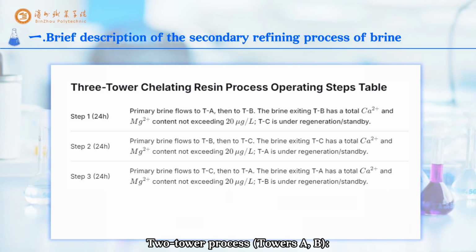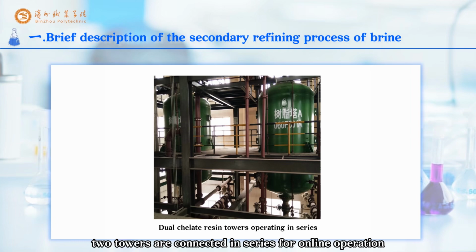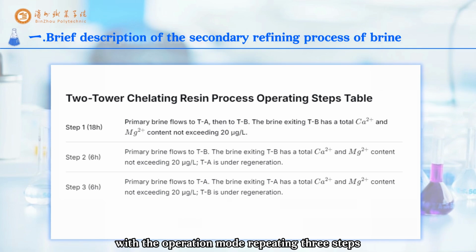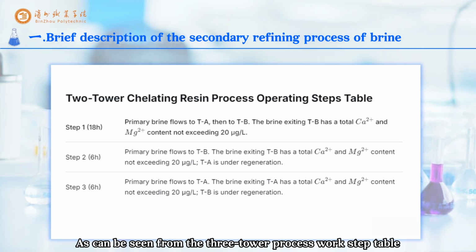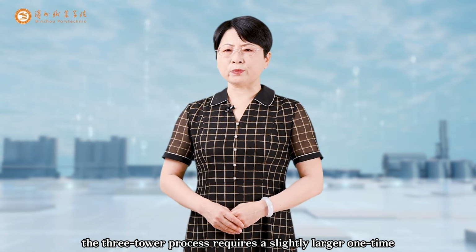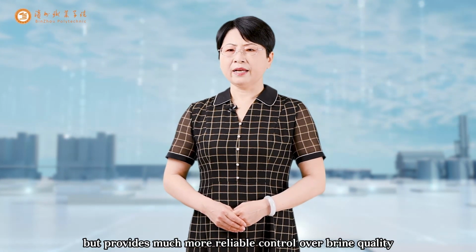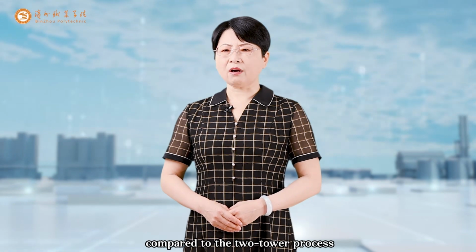In the 2-tower process, towers A, B under normal circumstances, 2 towers are connected in series for online operation. Then, 1 tower runs online and the other is offline for regeneration, with the operation mode repeating 3 steps. As can be seen from the 3-tower process work step table, the 3-tower process requires a slightly larger one-time investment, but provides much more reliable control over brine quality compared to the 2-tower process.